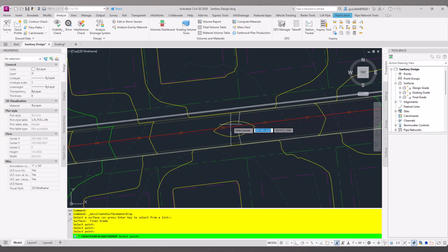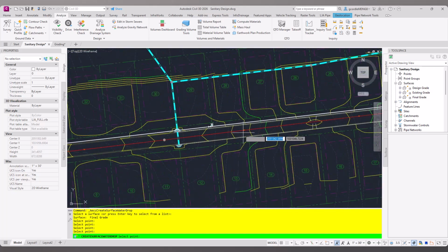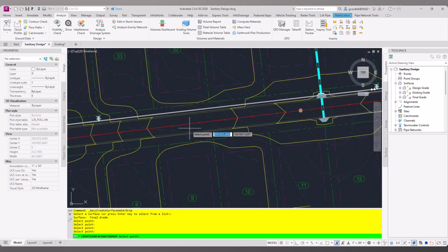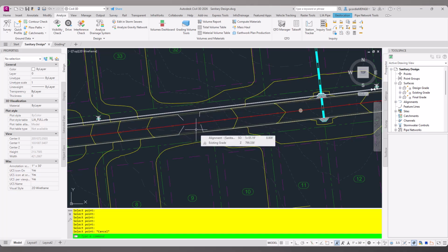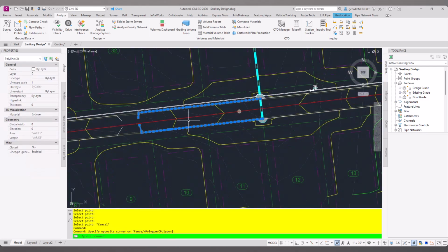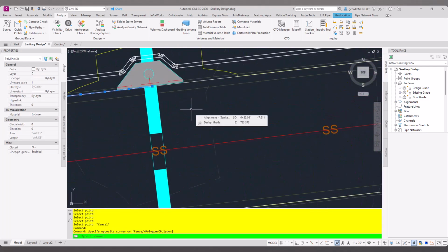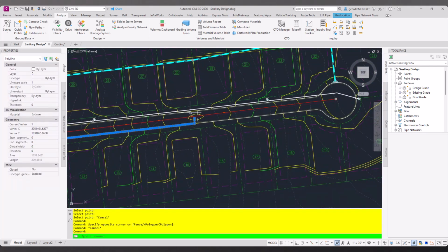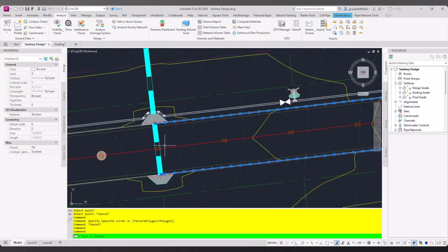And I'll do the same thing on this side here. Yeah, it looks like everything's going to the catch basins. I'll take a look at it again in a second. Here I'm going to select about here, and then I want to select it right in here. Same thing on both sides. And what I'm doing is, again, putting this water drop and figuring out where it goes. So let me make sure I have my low point for these catch basins here for my surface. So if I select both of these 2 lines here, it looks like both of those, that water drop is going right to where I need it to go in that catch basin. If I select these 2 here, yep, it's going right to it.